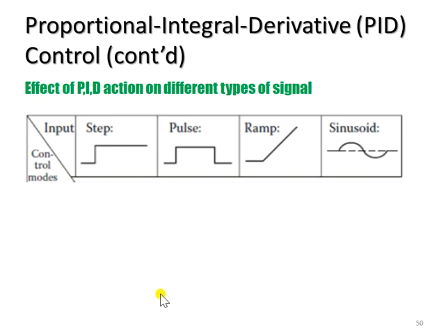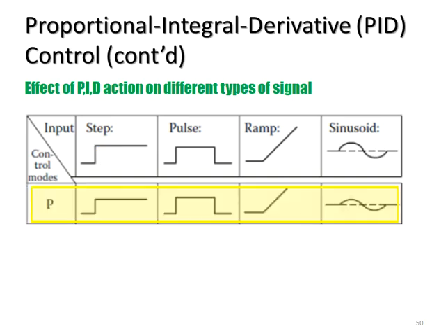So we are going to consider the first controller, which is the proportional controller. The proportional control, as we understand, the function will be similar to the error signal, as we only multiply some value of gain to the value of error, so it will replicate the error shape similarly. The only difference is the magnitude of proportional signal.